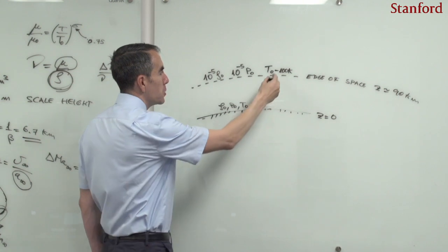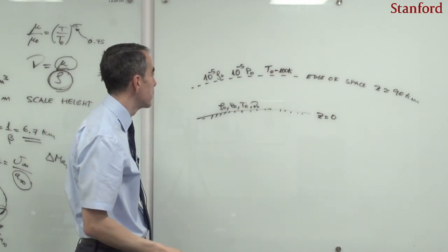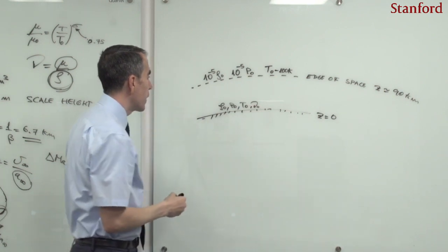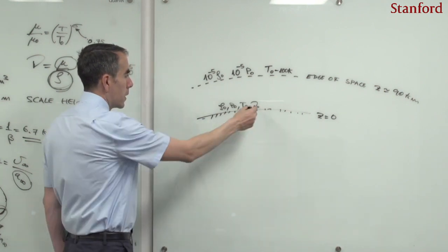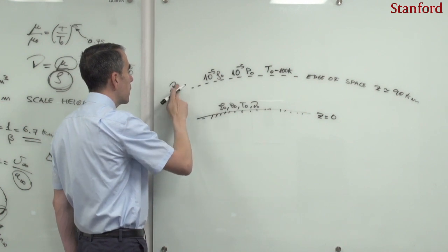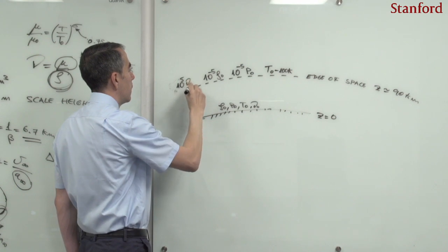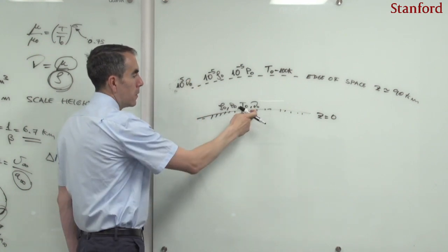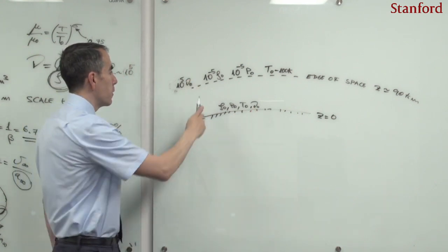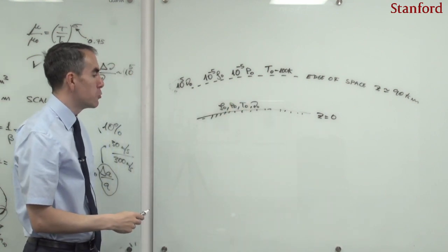And this variation is not monotonic, so it's going to be doing wiggles and all of that. And then for the kinematic viscosity, we know that this kinematic viscosity here is going to be 10 to the 5 times larger than the kinematic viscosity on the surface. So these are the type of conditions that a hypersonic flight system needs to deal with.